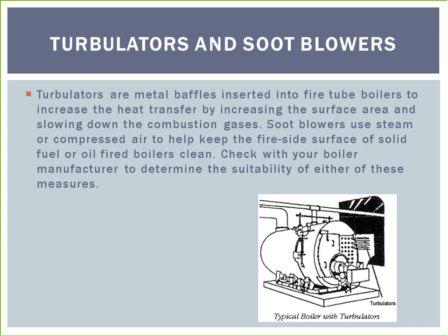Turbulators are metal baffles inserted into fire tube boilers to increase the heat transfer by increasing the surface area and slowing down the combustion gases. Soot blowers use steam or compressed air to help keep the fireside surface of solid fuel or oil-fired boilers clean. Check with your boiler manufacturer to determine the suitability of either of these measures.